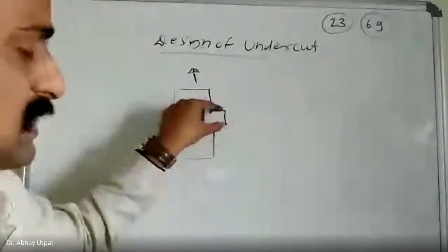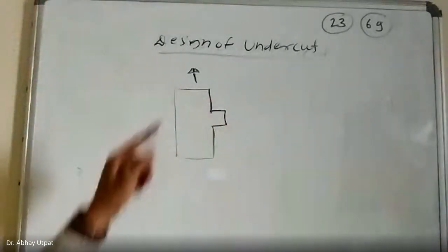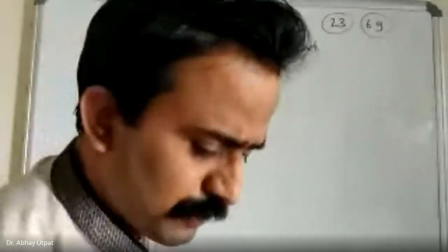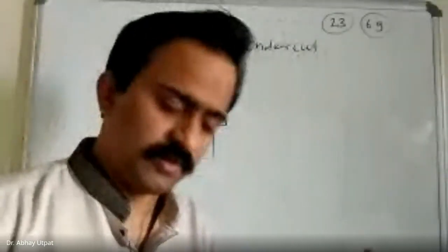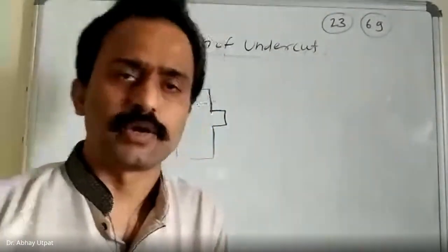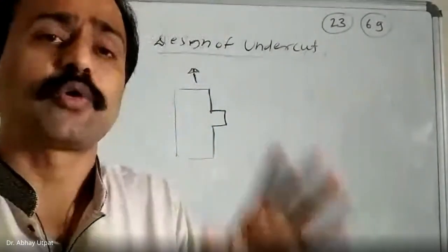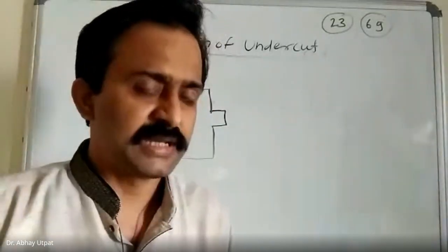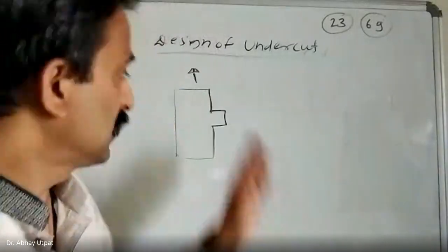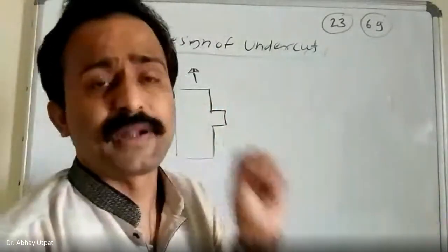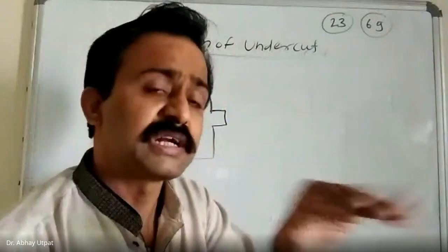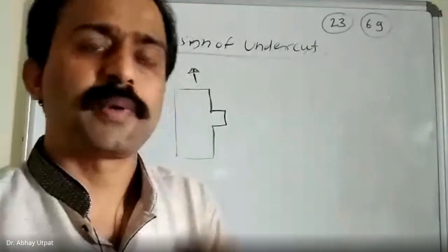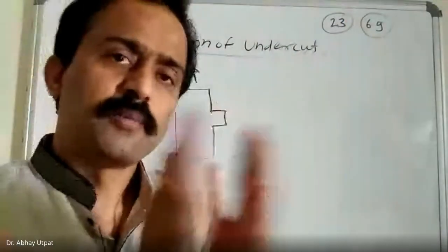So in such a case, if some undercuts are there, you can strip them for removing purpose. Undercuts are nothing but the obstacles or extended parts in the work component or your workpiece which may cause difficulty in removal with the help of ejector pin. I repeat once again, undercuts are nothing but surfaces which are perpendicular to ejector pin movement or mold movement.